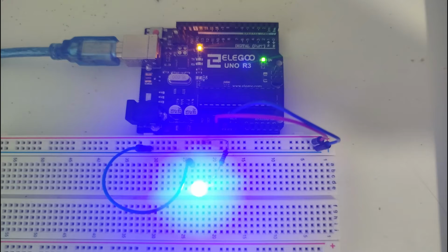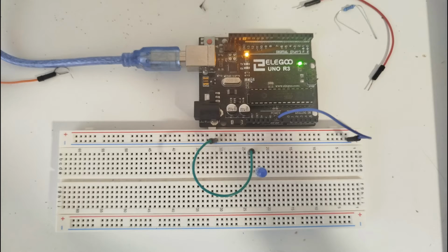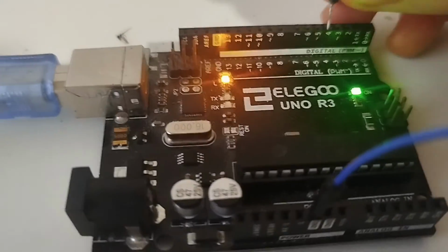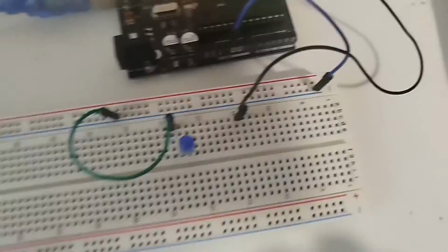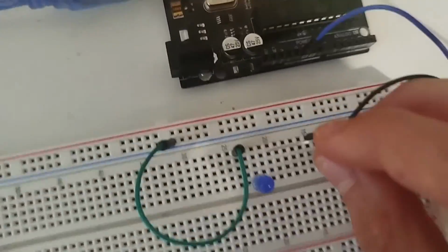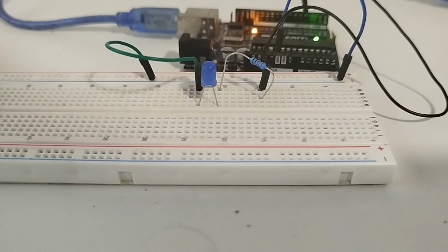But 5 volts isn't cool, it's just always on, we want to be able to code it. And to do that, we'll use these pins I mentioned. So let's get rid of the 5 volts, get a jumper wire from any pin, I'll choose pin 4, to some line, and then connect that to our LED's positive through a resistor. And that's our wiring done. Now let's open the IDE.